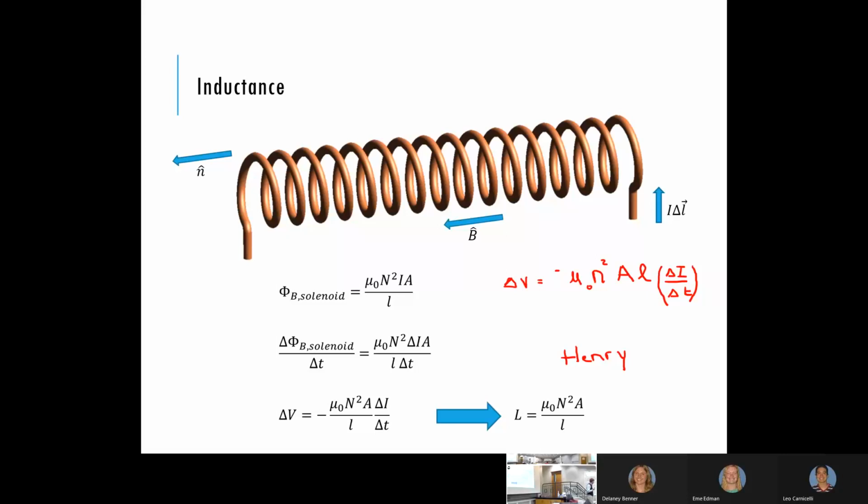Usually how I can tell the difference is that a capacitor, like I said, is cylindrical with a silver top. An inductor won't have that silver top on it. And usually an inductor will have the electrodes coming out of opposite sides. So with a capacitor, the connections will come out on the same side. Inductors also tend to feel really heavy. If you put a capacitor in one hand and an inductor in the other, you'll notice the weight difference, because literally it's a coil of wire, so it's going to be heavier. There's more material there, more metal.